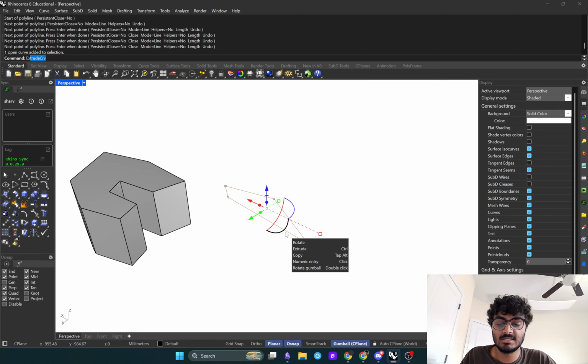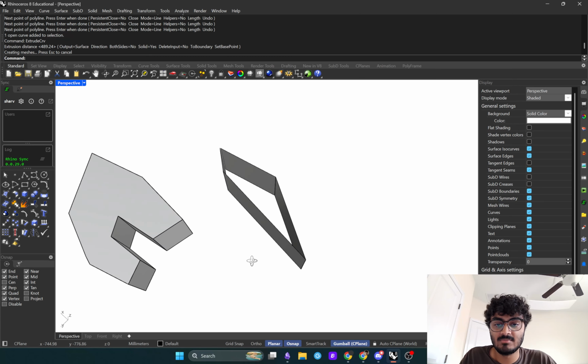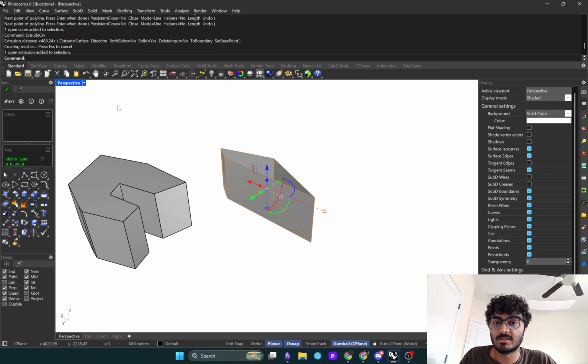This is what happens when you extrude a curve that isn't closed. I'm going to select it, and I'm going to try to do the same thing as last time. I'm going to click over here. It's using this height as a reference, so I'm going to click over there. You can see that it didn't make a solid shape, and when I click on it, it says it's one open extrusion.